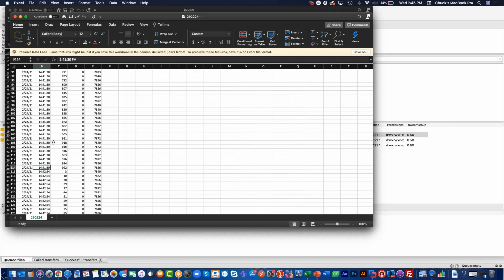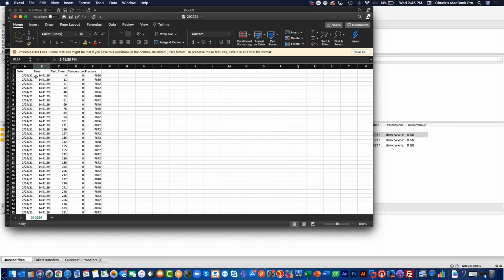This was for the second test I ran when I couldn't see the file. So from 114 all the way up to 2, that means we were able to get 113 samples in a 1-second test. So our sample rate there was a little bit faster than 10 milliseconds. That should give you an idea of some strategies you can use to still use the standard data log object, but take samples for your data logs at much faster than once per second.